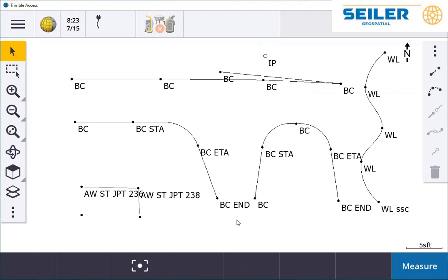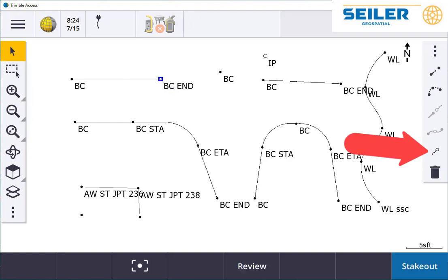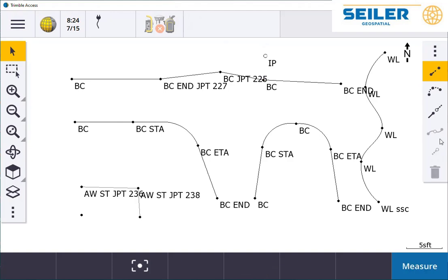There is no insert command available, but what we can do is build on what we've talked about. I can highlight a point, end that chain, highlight this point, end. Now, using the join command, I can pick the points and connect them in order. So if I missed a point along the way and I went and reshot it, I can use the CAD Toolbar drawing mode to insert it properly inside the chain. There is no undo, but this is just the beginning of the CAD Toolbar.